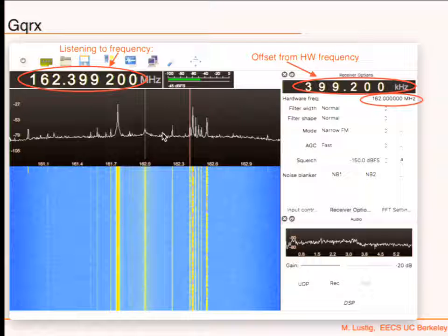All right, so now that you maybe kind of get it, but kind of don't get it. The complex value doesn't come from the sensor, it comes after the filter. It comes from the way we represent the data. The data is real. I mean, this is 162 megahertz. I'm not giving you the whole spectrum. I'm just giving you 2 megahertz of the spectrum. Right? But the sensor is still sensing real values. Absolutely. It is sensing real values. That's right.